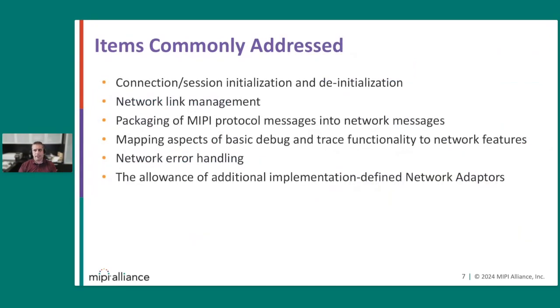So this family of specifications is addressing, again, the same thing, just over different interfaces. You can see here the items that we really focus on in this family: how do you set up the connection to those protocols, and session creation, and how do you initialize it and get it set up, and have that contract between the DTS, the debug and test system, or your debug tooling, and the target system, the thing that you're debugging, right? How do you do that? We address management of the link. How do you make sure that's all set up correctly, that you're getting into that stream with maybe the non-functional traffic, the non-debug traffic as well, getting that in there.